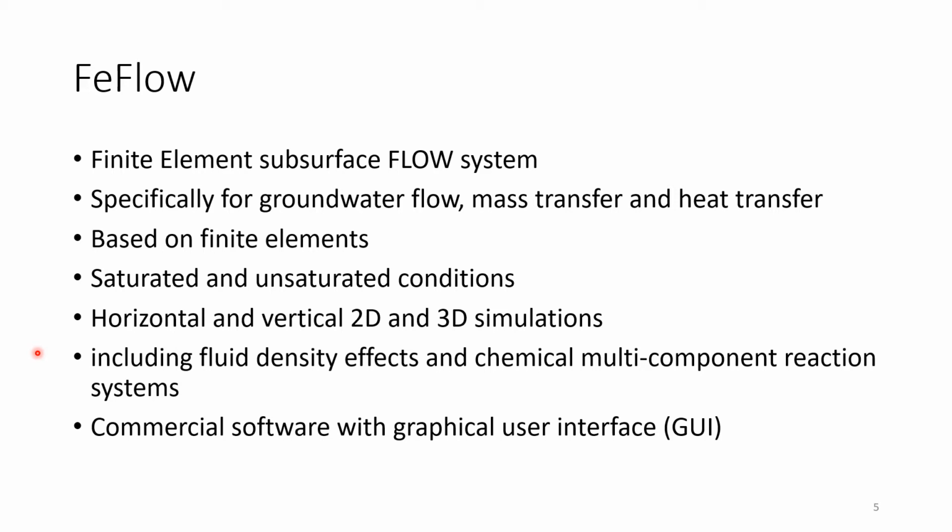As the name already says, FEFlow is a finite element subsurface flow system. It is based on finite elements, right? That's quite clear by the name. It covers saturated and unsaturated conditions, so you can also do infiltration modeling with this. It has horizontal simulations, and for infiltration you can also have vertical simulations, and you can even do full 3D simulations with it. So there is quite a big capability of using FEFlow for groundwater simulations.